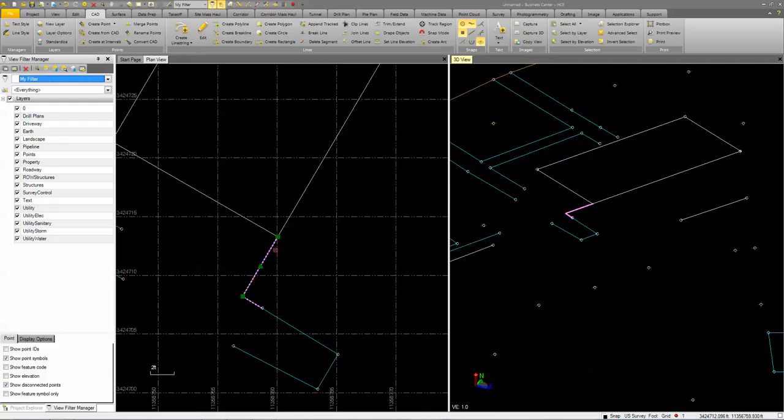Now with that, let me close this. You'll notice that when the line is selected, depending on which segment I select, it's going to add the grips. It's not adding grips to these because those were drawn by those lines. But if I grab this one, I can take this grip, left click and hold, and drag it to a new location. I can come over here and drag it right back. If I grab the triangle, I'm able to move that whole segment accordingly. Then do a Control Z, or an undo, to send it back.